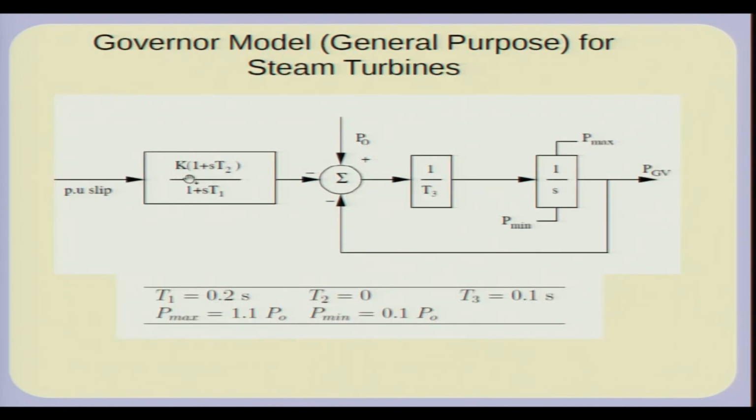Here I have shown a proportional law. So, proportional law is also called a droop controller. Especially if the proportional controller has got small gain, then to get a certain output you need a larger error. Okay. So, you will never be able to achieve a 0 error, that is you will never be able to achieve perfect regulation, and that is called droop regulation. Now, in case you have got an isochronous governor, you will have an integral controller, and this can be made to go to 0. Okay.